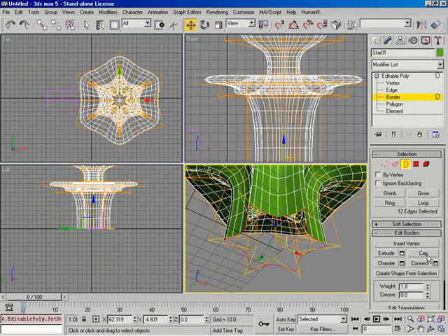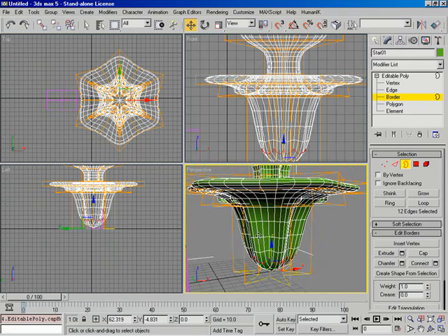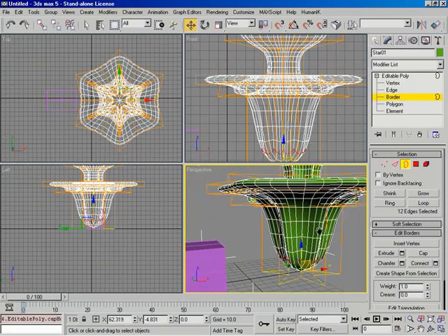Now when I cap this, it's pretty interesting to note. It's not like it's just butting up a new polygon face to the end of your shape that's already there, or your geometry that's already there. It's actually basically welding a whole new polygon into the whole geometry itself. In other words, we won't have multiple vertices at all of my edges right here. It'll just be a single vertex at each edge. So take a look. Cap, and you can see I just proved my point, because now it looks like my geometry right here was smoothed out from the very beginning. Okay? Right, like as though it was already capped before you started applying the NURMS subdivision. You got it. Absolutely. So there's just a quick look at that.